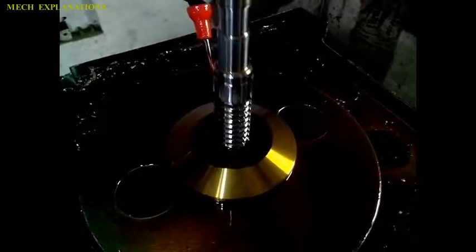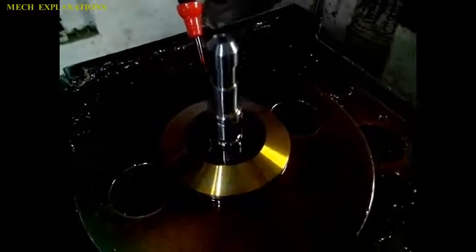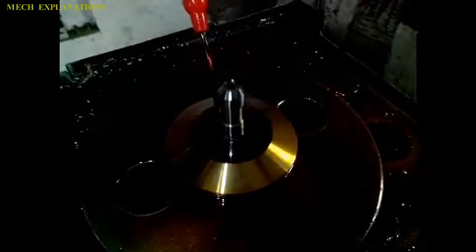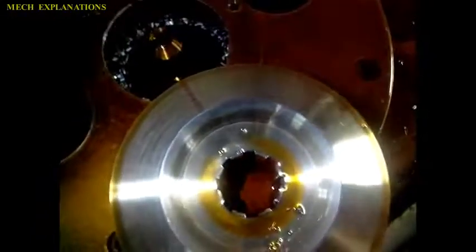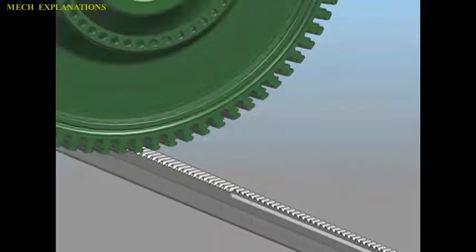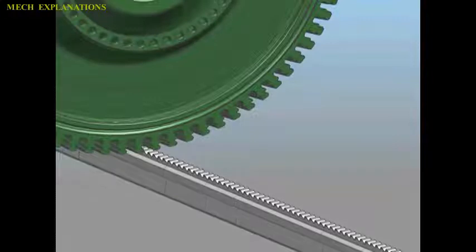Broaches are shaped similar to a saw, except the height of the teeth increases over the length of the tool. Moreover, the broach contains three distinct sections, one for roughing, another for semi-finishing, and the final one for finishing. Broaching is an unusual machining process because it has the feed built into the tool. The profile of the machined surface is always the inverse of the profile of the broach.